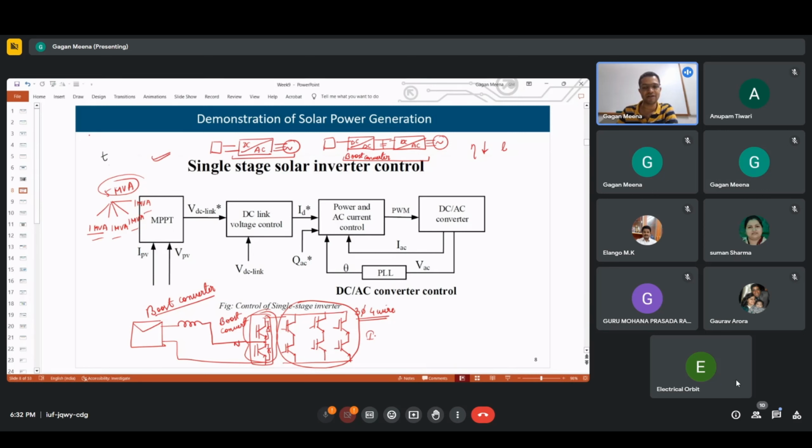So this storage is behaving like actual storage. But it will give voltage and current at a very high value, right? Say 10 ampere, maybe 50 ampere, 15 to 20 volts. But this RTDS can take input only within plus minus 5 volts. Now we need to scale these. In between we need some interface. These are called power amplifiers.